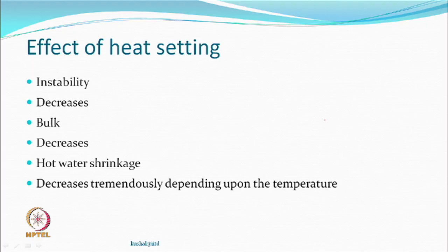And the hot water shrinkage, obviously you are stabilizing the structure, crystalline content may increase. So, you have a stable structure. Whatever happened, happened. If you allow shrinkage to take place during this heat setting process, you have allowed. But now the final yarn which you get and test is going to be more stable, because you have allowed all the shrinkage and relaxation during the heating process. All right. So, the final yarn is a stable yarn.